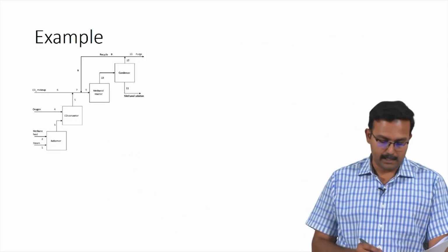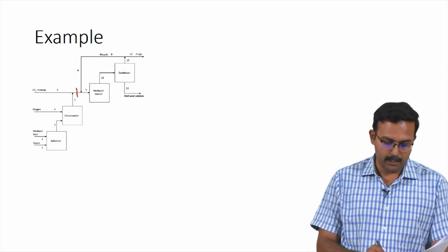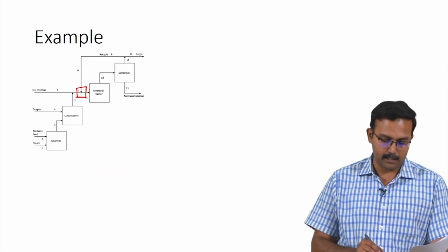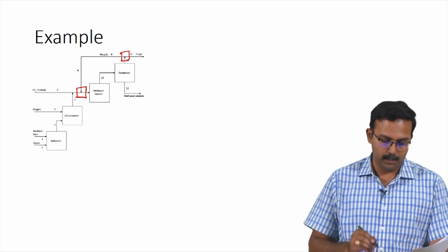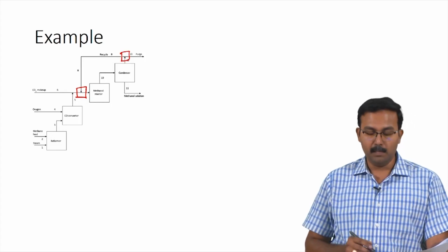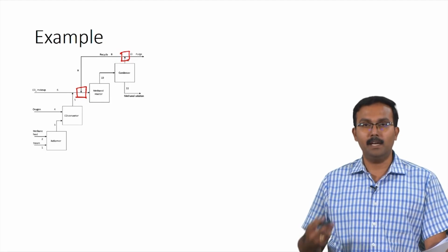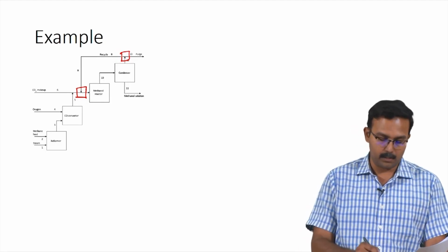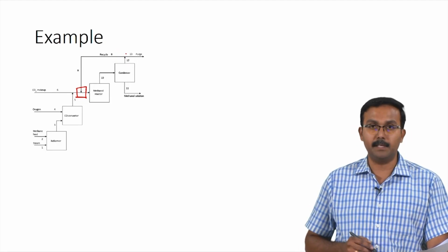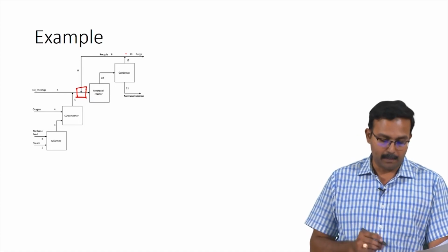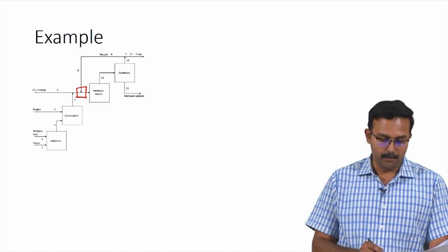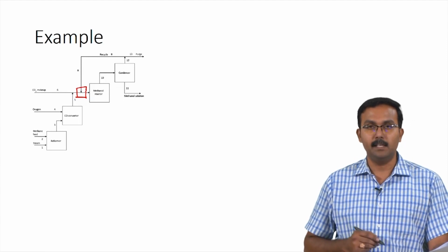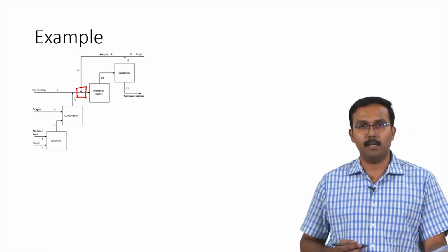For calculating the recycle stream, we would like to write a balance equation for either the mixing point or for the splitting point. The problem with the splitting point would be we would have only one independent balance equation. So, it is better to write the balance for the mixing point. For that, we would have to have information about stream 9. How do we get information about stream 9?